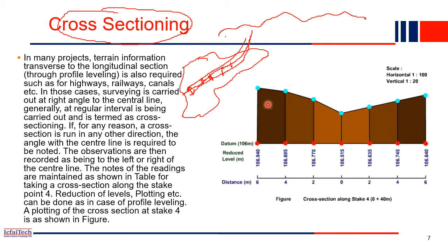The road here is not flat, right? Cross-sectionally also the road is not flat, you understand. So here also profiling is required. With this top portion, maybe you need to cut it and fill it somewhere here, so that the line should be flat, or maybe somewhere like that you can take it. Okay, let me draw it. Yeah, so this may be the road. So this top portion you can cut and you can fill it here. So that is the advantage of using cross-sectional profiling.